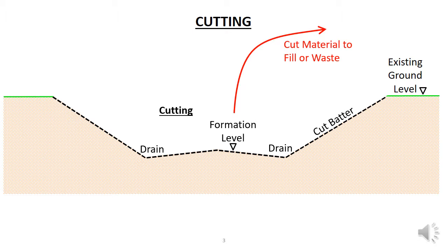This is particularly a problem with non-cohesive soils, such as sands and gravels, which rely entirely on the interlocking of soil particles for their stability and are easily eroded unless they are protected with topsoiling and grass, sprayed concrete, netting, or another type of covering. Therefore, the batters need to be designed to maintain stability over long periods of time in all weathers. The stable slopes for a batter vary with the materials. Some rocks and residual soils can stand almost vertical, while sands and gravels need relatively shallow slopes and often need additional stabilization, such as sprayed concrete.